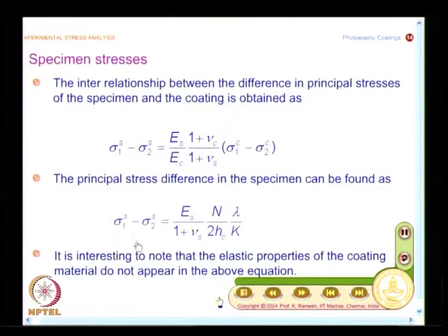It was not critical, because the loading is different. It is basically the strains that develop on the specimen surface that are transmitted to the coating. The level of loading on the actual coating is very small, and if you look at this expression, you can actually replace this by the yield stress and find out what is the maximum fringe order, and you will find that number is small. That also we will take up later.